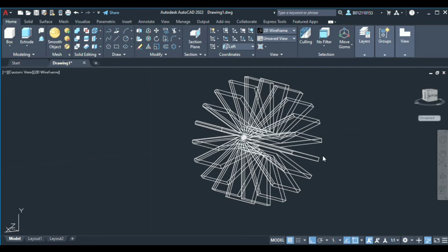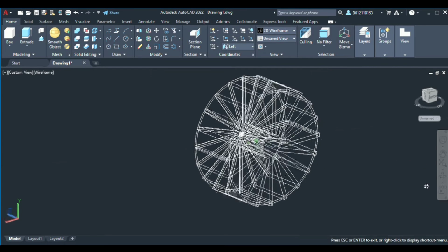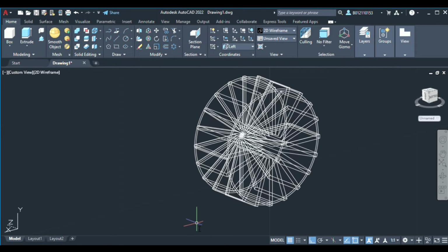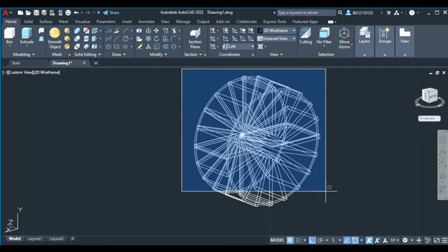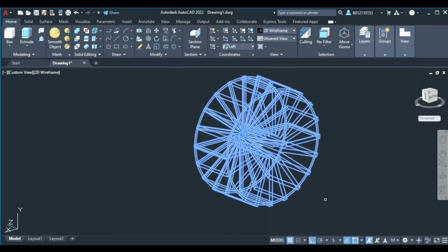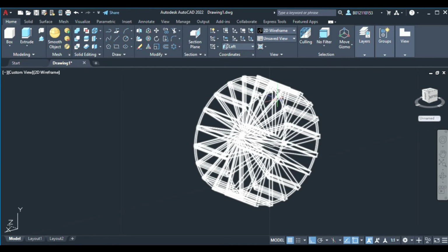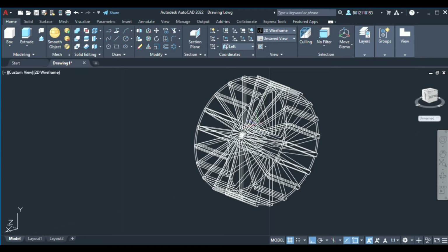And then let's get back the truck tire, which is this truck tire, and we use another union command and join these two objects. Press enter, and then it will become a single object. After that, like I said just now, we need to remove all the things inside the circle. So let's use the center here. Our radius of our inner circle is 3 cm. So press 3 and choose it here. We extrude until the end of our truck tire, which is 2.6, the width of our truck tire.